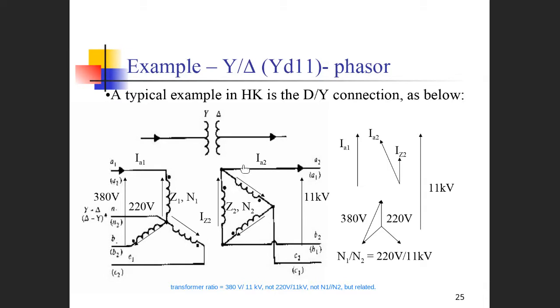For the high voltage side direct connection here, we can transfer it into a star connection, then take one star phase connecting with the primary star phase to form an equivalent circuit. So delta transfers to star, then take one phase out to form a per star equivalent circuit.